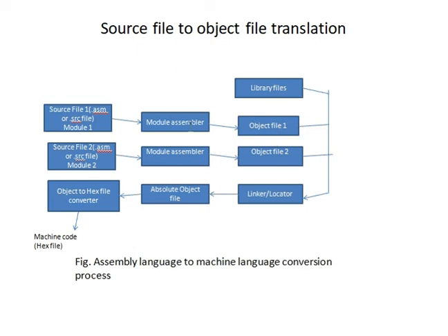For example, when you're talking about this .asm file, there are assembler directives which would talk about which region your code begins with, and also the data type of your variable which you're using. All are addressed in the assembler directives. It directs the assembler which region this variable has to go to, which region this program has to go to.